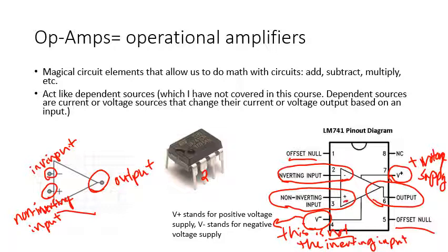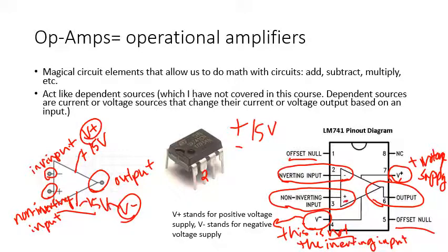So we normally give it both a positive and a negative voltage. Most commonly, we use positive and negative 15 volts. Some of the time you will see this on your little triangle diagram for an op amp with an extra line vertically going to the positive voltage supply, that's V plus, and another line going down, that's the V minus supply. Again, without giving it those voltage supplies, our op amps will not do what we think they do. So they do always have to have a voltage to power them.